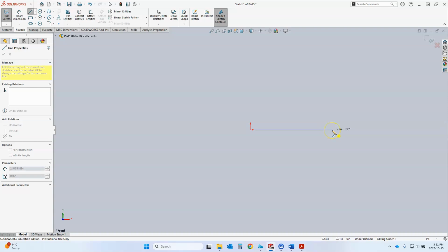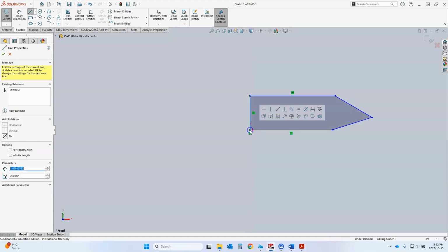So I'm going to pull it out to about here, left click, come up to a point about here, left click, come up here somewhere, left click. Focus on, again, making this horizontal so you can see that yellow box with the line through it. And then once we get close, it's going to try to line up with our origin, which is what I want to do. So left click again. Come down and hover over that origin point. You can see the line changes to sort of a donut shape on a yellow background. Once it's there, we're going to left click again.